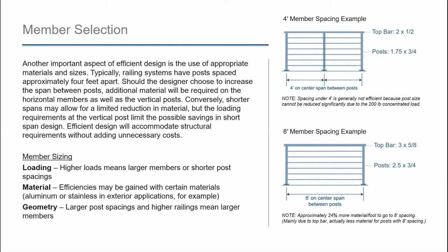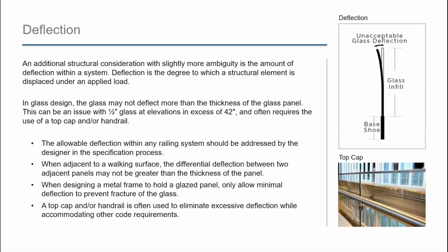Railing that's fixed or grouted into concrete, however, requires more detailed analysis and may require special detailing. We don't have the option of putting slots and base plates on those types of railings. This is especially true when you're using aluminum, because aluminum expands and contracts more than steel or concrete, so you can induce some pretty large loads if you don't have special detailing.